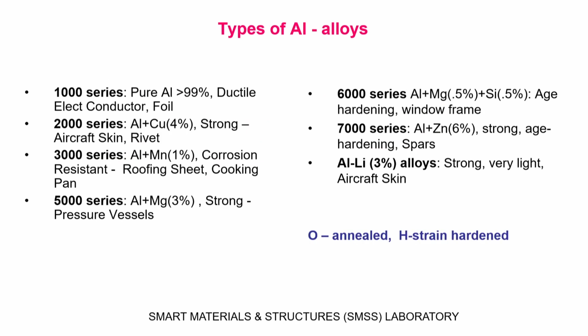But before I talk about that, I also want to tell you how complex the material selection process is. Just consider one material which I told you is very popular today, aluminum and its alloys. Now, aluminum and its alloys actually have 7 to 8 series, like let us say the 1000 series, one example, which is nothing but pure aluminum, 99% pure.